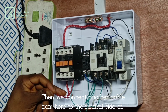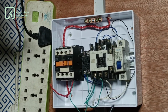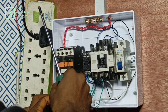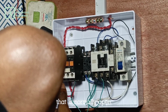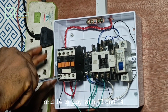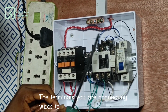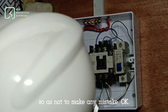Then we connect another cable from here to the neutral side of contactor 2. So find out the one that is normally open and connect. In my own case, I have 13 and 14 to play with. So these two here are normally closed, while here and here are normally open. So you must be sure of the terminals you are connecting wires to, so as not to make any mistake.